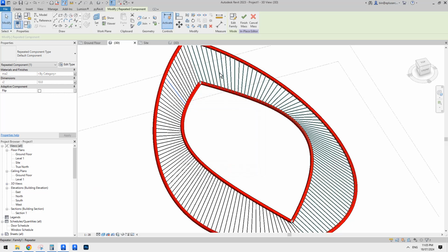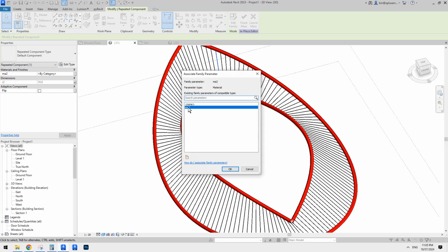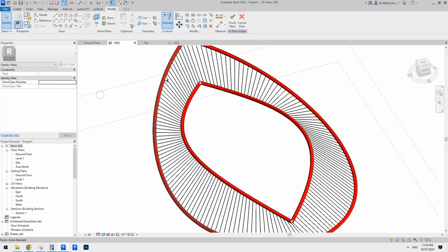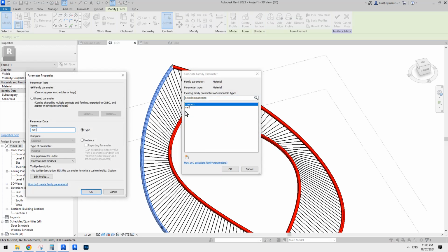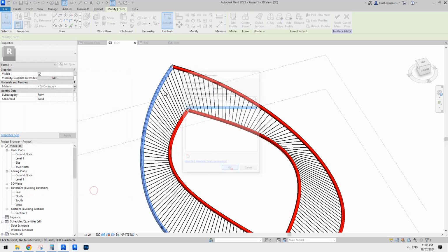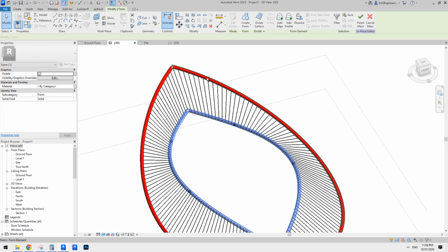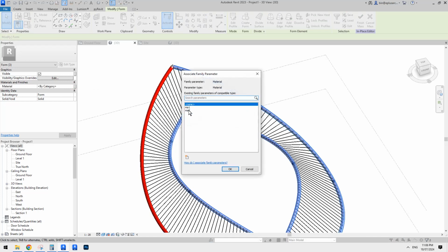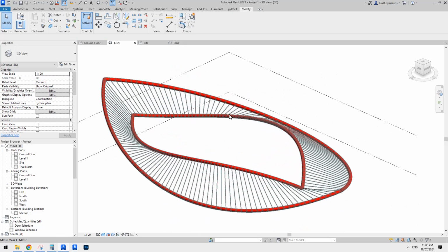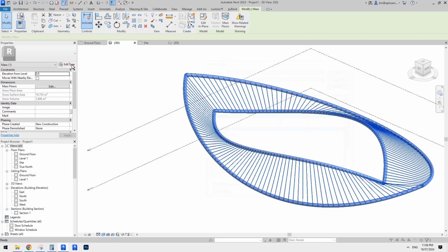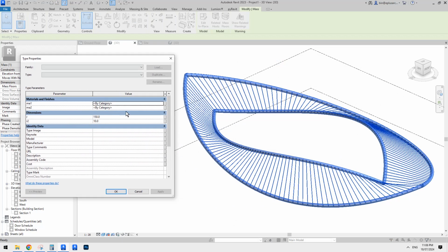Okay. And then select one of these families on this side, and also link this one to MA2. And okay, so we also need to control MA1, right? So let's create MA1 for the bigger one. So same, I'll select 1, 2, 3, and MA1. So now if I finish this model in place mass, let's try again. Select this one, edit type. Okay, so now we have all the parameters. Yeah, I think it works. Type 30, increase the number. Oh, sorry, increase the radius.